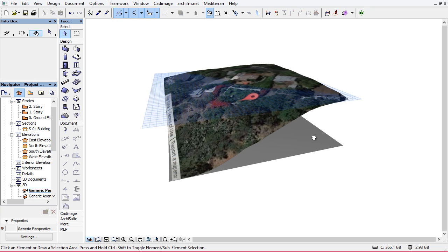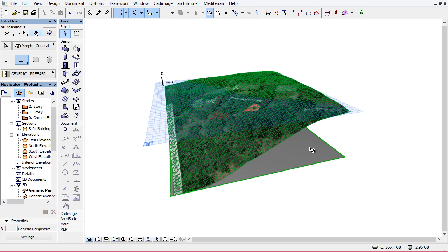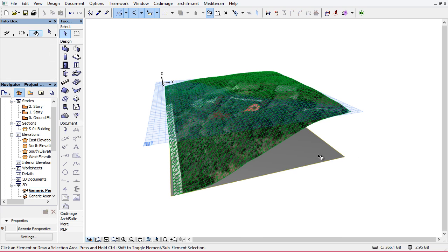And prior to multiply, I have to do this tiny little nifty thing, which is to give this morph a bit of thickness. Okay, it's important. If you don't do this thickness or this little extrusion to the surface of the morph, we're not gonna get anything.